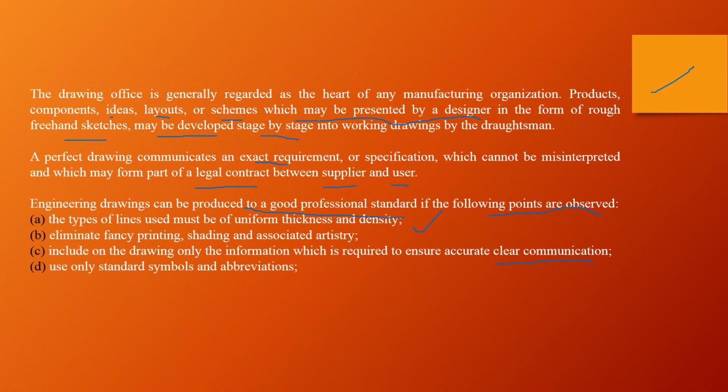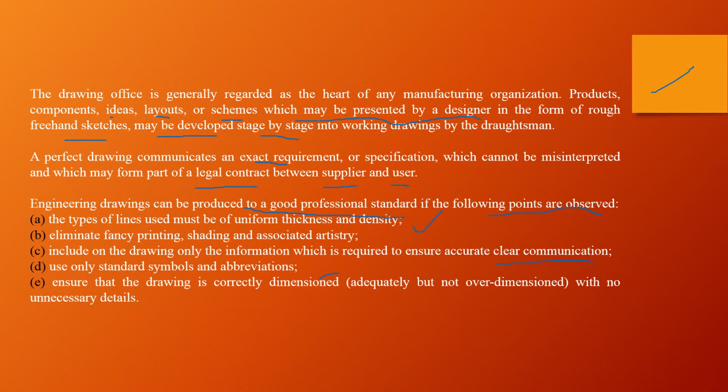Use only standard symbols and abbreviations. Ensure that the drawing is correctly dimensioned with no unnecessary detail. Adequately but not over dimensioned, meaning there are no unnecessary details.